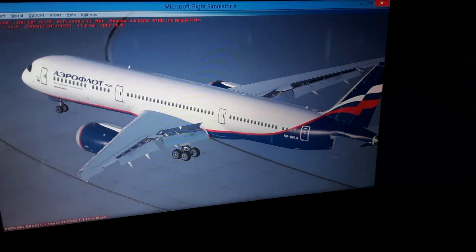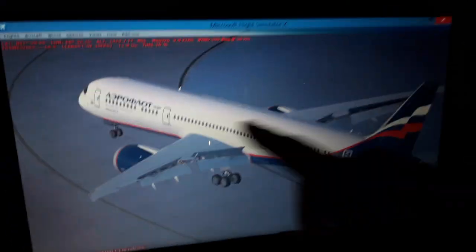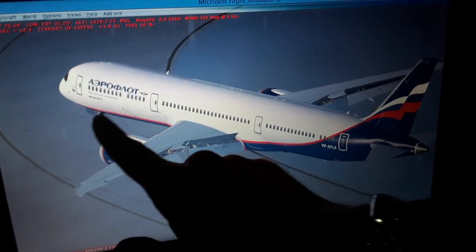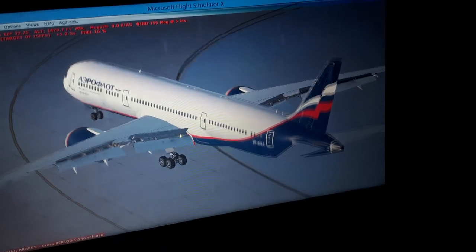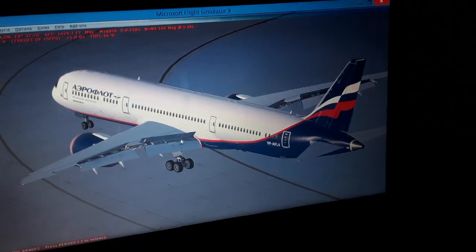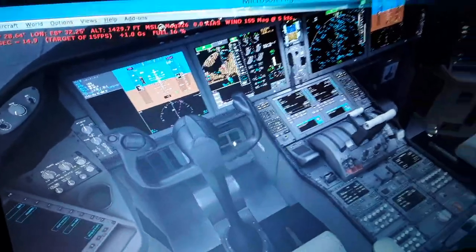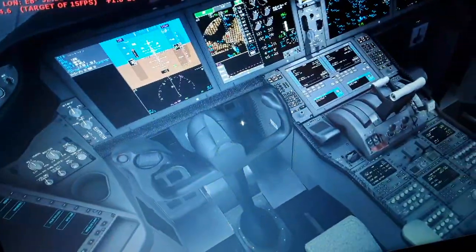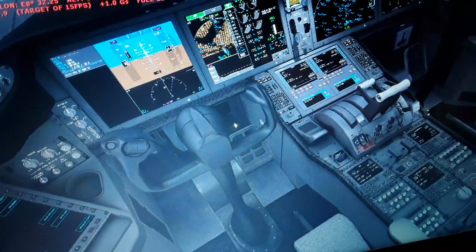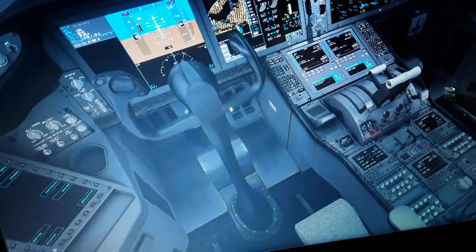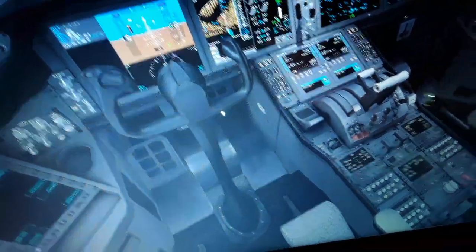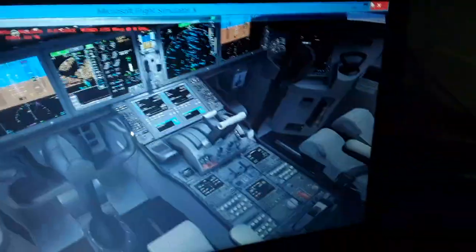So at low airspeed, when we initiate the takeoff, the nose wheel is also used for directional control, the going of the aircraft. For that I have the rudder pedals mapped here, so you can see. We move the rudder pedals, left rudder and right rudder, and the rudder pedals are also used for controlling the forward nose wheel steering.